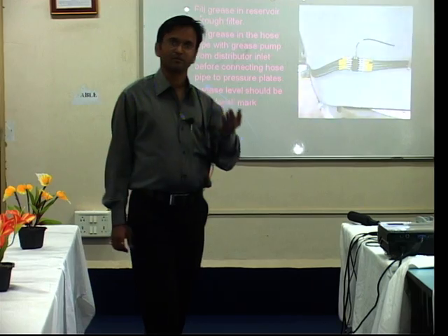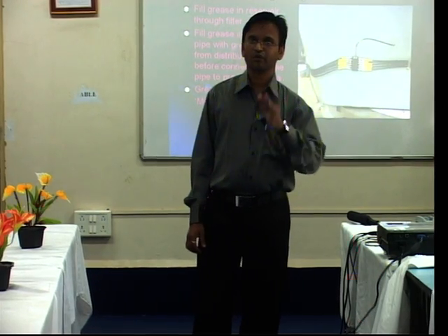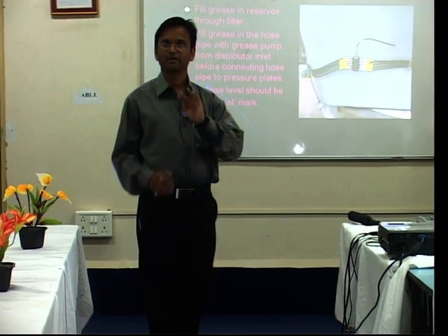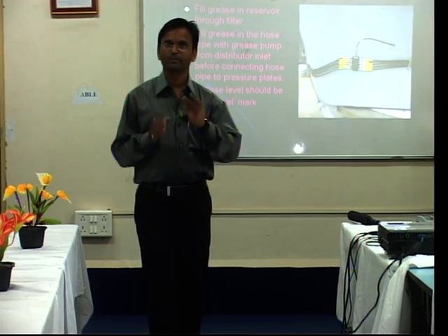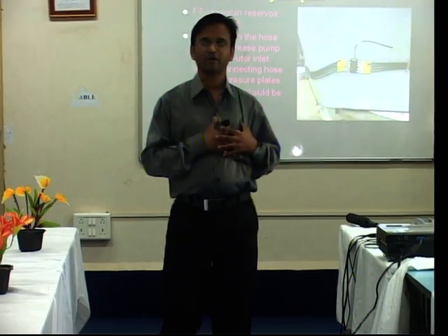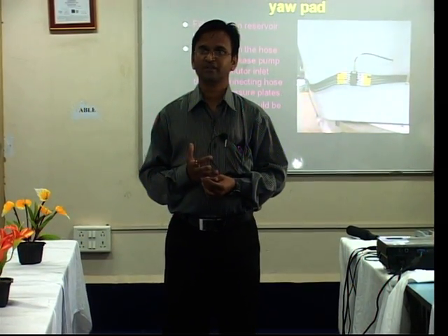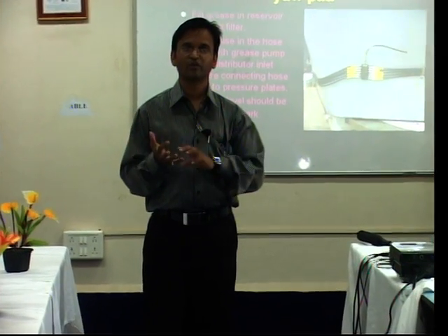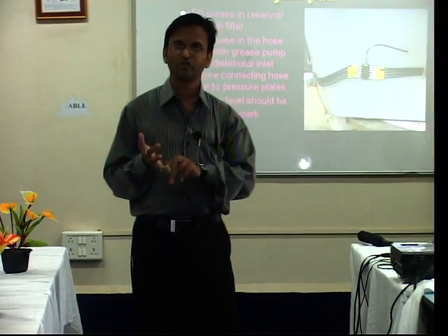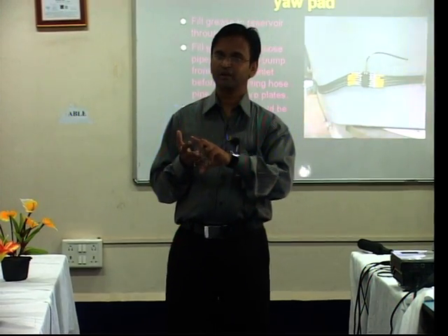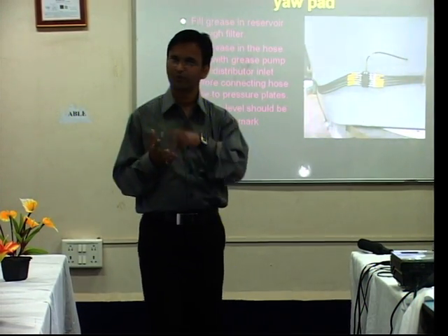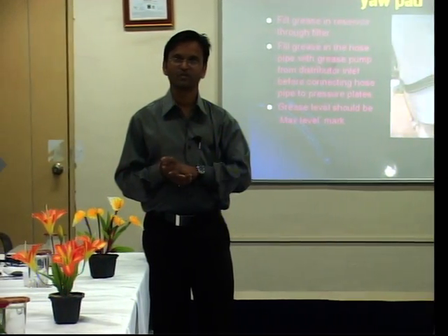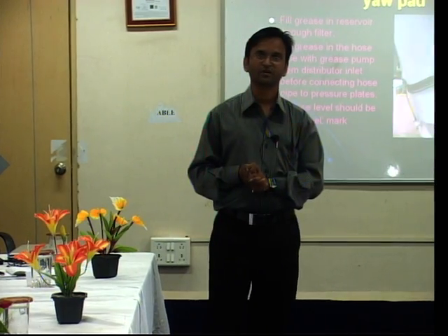The nacelle assembly is kept on the yaw mechanism, and this assembly contains the generator, gearbox, coupling, and controller. The controller is one of the important members in a wind turbine, handling various types of data, such as speed, motion, velocity, and the temperature of the oil in the gearbox, and so on. This is the discussion.